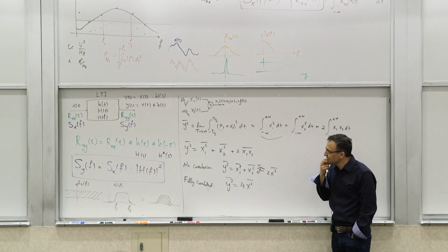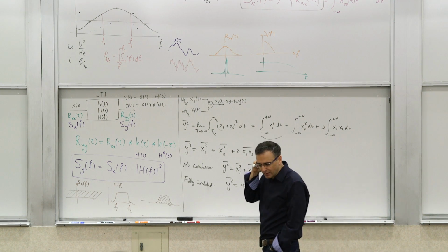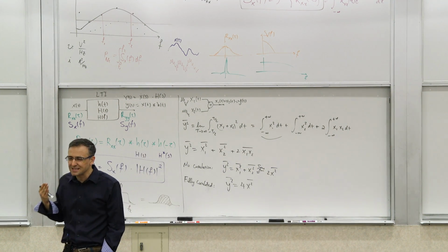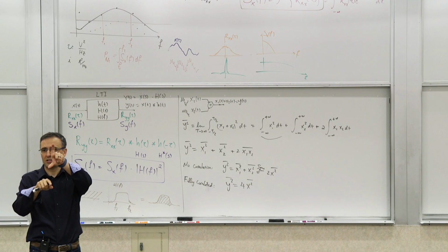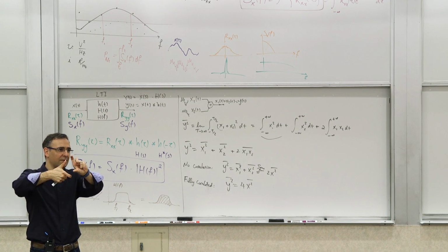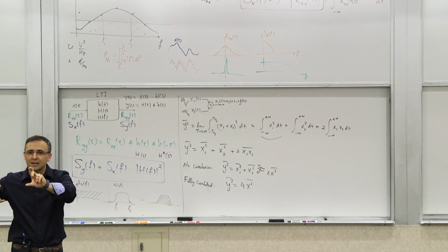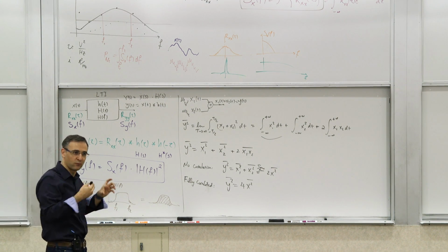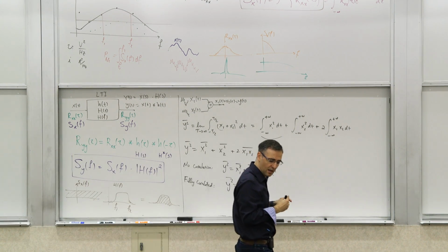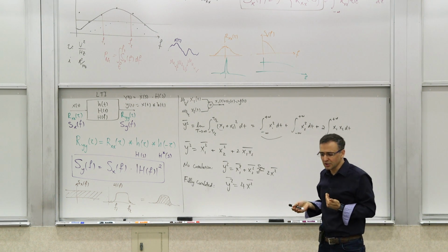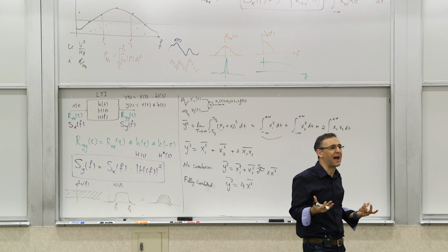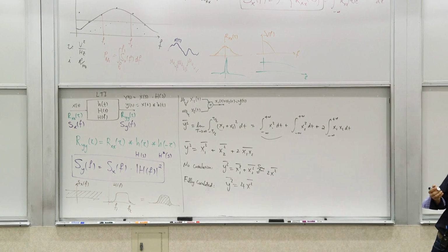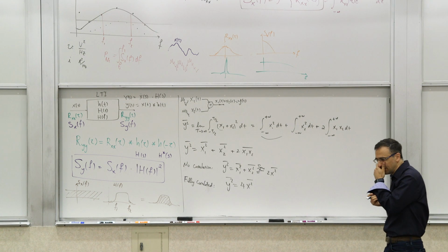So this is interesting. To get a sense of what full correlation means: it means 2 waveforms that are related to each other by a scalar. So 2 waveforms that look the same, where one of them is larger than the other, or one of them is exactly the flipped version of the other if that scalar is negative. For it to be fully correlated, 100% correlated. Now, in general, 2 signals can be partially correlated, and then you can define a correlation factor, the ratio of the correlated part to the total power that you can have.